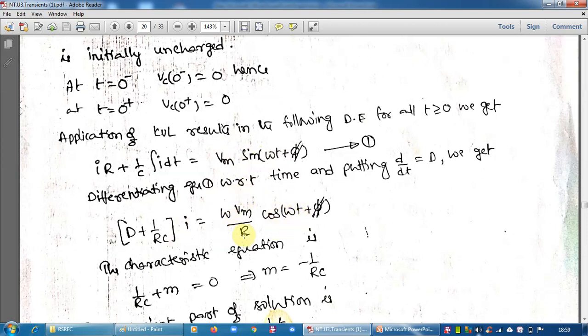So the RHS value is something. Previously, as we had 0 here, the response for the RC circuit was only the transient response. No steady state response. You remember or not? For an RC circuit excited by DC supply, the complete solution consists of only the transient response, I equal to IT only. Why? Because here we are getting 0, that means a homogeneous equation, no steady state. But here for AC circuits, no 0. It is a non-homogeneous equation. We have both transient response and steady state response.